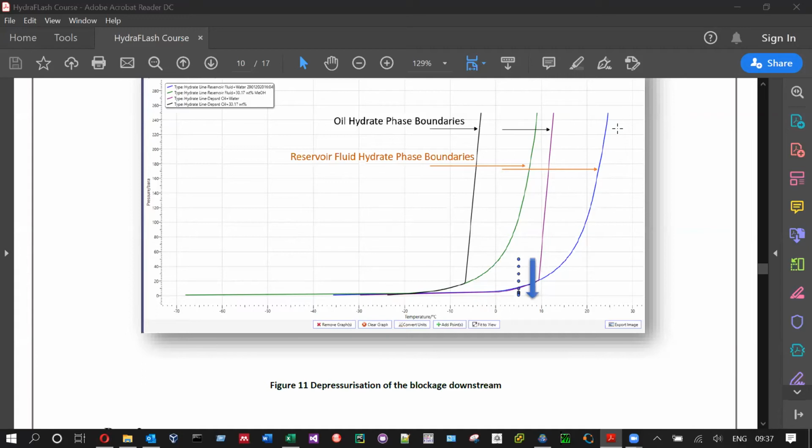This means that there is a very small possibility of blaming hydrate as the problem. The reason is that if hydrate forms, it will change the composition and we take away a strong hydrate forming compound. So when we depressurize, some hydrate will dissociate, and in most cases the fluid can be mobilized.